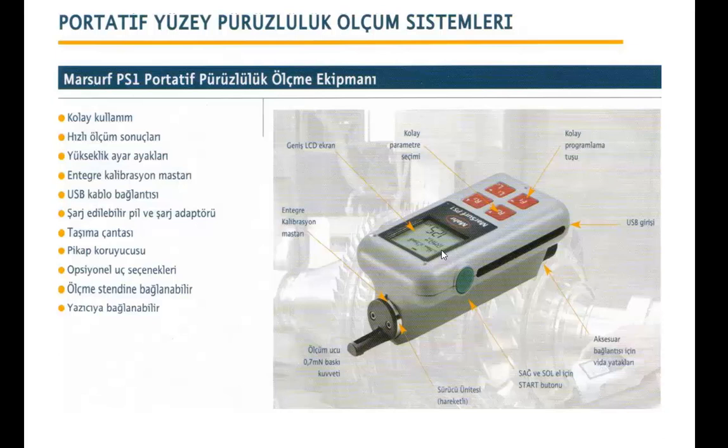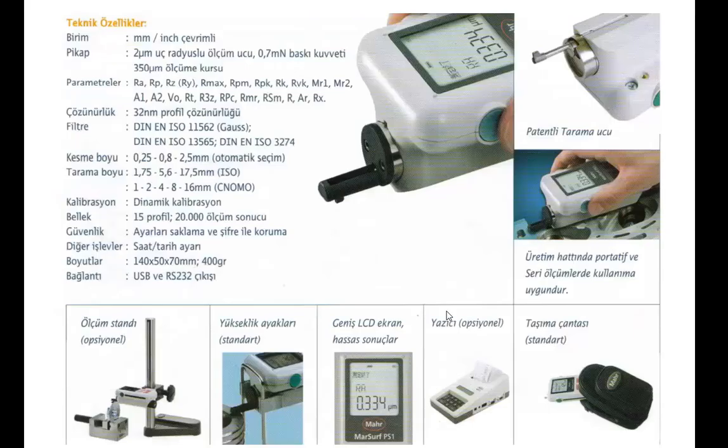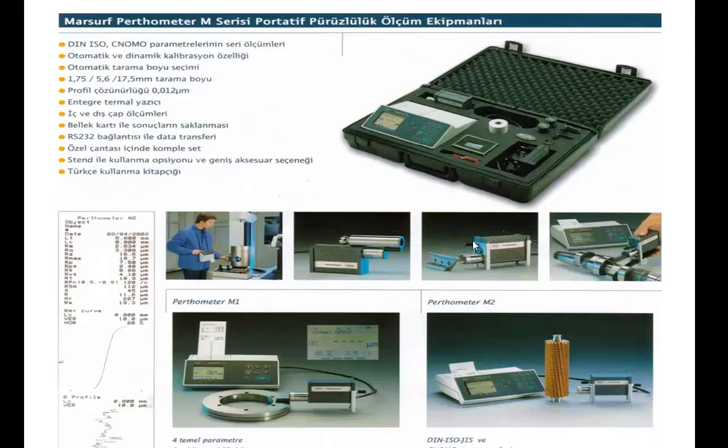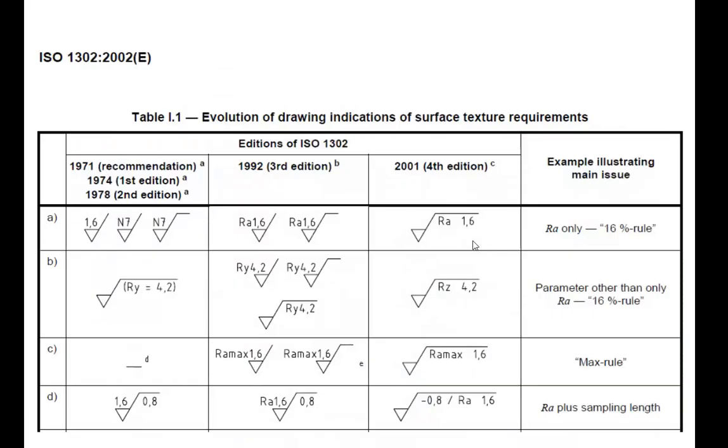From the display we can directly see the measured value, average roughness height. For instance, this is the probe, and there is a stylus over there. Bring the stylus into contact with the surface of the body, and then pushing a run button can sample the irregularities over the surface.